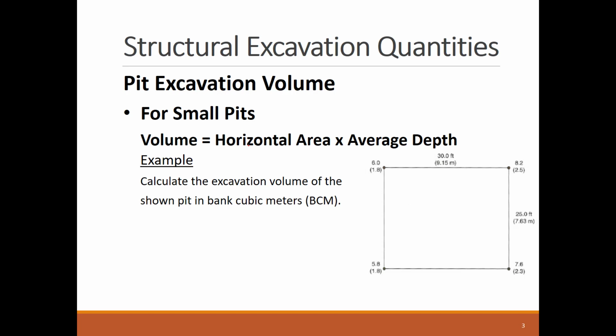First, pit excavation is performed to remove the soil to reach the specified level for constructing the foundation of a building or other similar structures. We'll see how to calculate the excavation quantities for both small and large pits. As in the shown formula, the excavation volume equals the horizontal area of the pit multiplied by the average excavation depth.